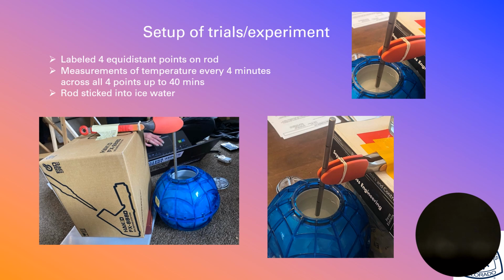The outer surface of the jacket was made of an insulating plastic layer, which basically just helps maintain a fixed temperature. Ice was packed into the external chamber of the jacket, and the internal jacket was filled with cold water. To check the temperature of the fin, we used an infrared thermometer on the fin and water until they were relatively constant, meaning that the system is at steady state. The 2 cases tested for the temperature data were with and without the fan, and we collected data upon that.